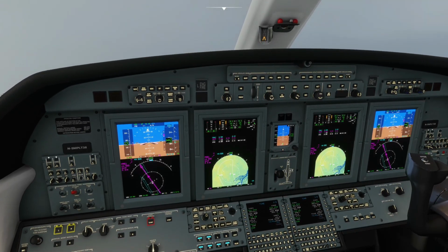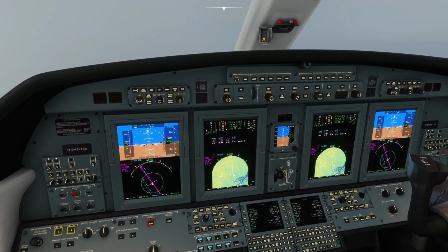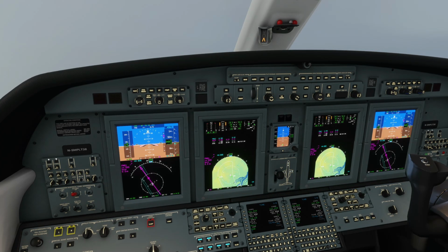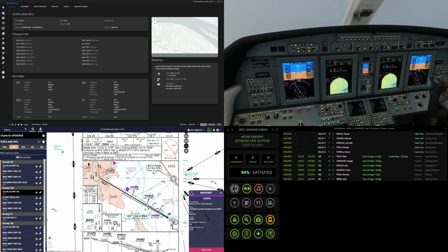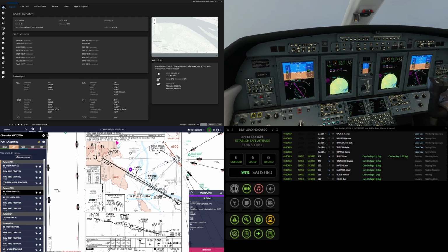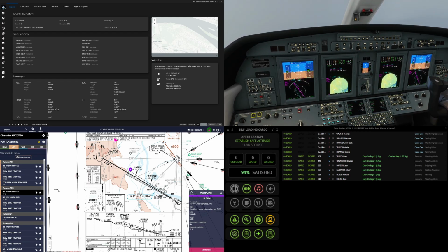Because it's CAPO, I will put the approach plate in there here in a second. Our approach plate says we enter at 4,000 at CAPO and then 3,100 at HEARN, 2,000 at POLES, and that's where we should expect to capture the glide slope. So our initial approach fix is CAPO, which we are traveling towards right now. Unfortunately without vertical lateral navigation for some reason.